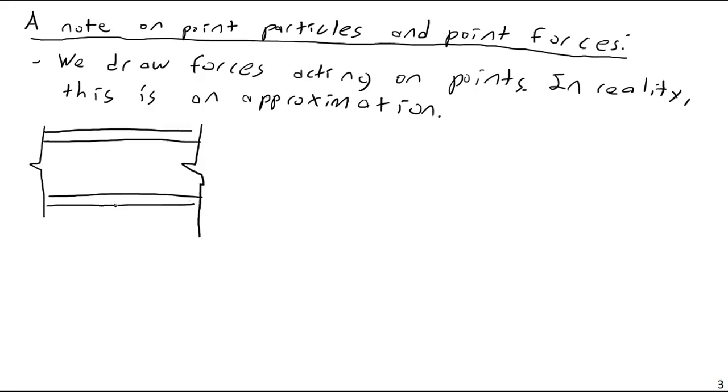It's just a piece of a beam. Then there's a little pad eye here, like we talked about yesterday. And from this, I hang a chain. And to this, I attach a big weight. So, how I would model that is, if I have my beam, I could have my beam line. And I would model that as a point load, a point load P. But in reality, that's actually just a model.